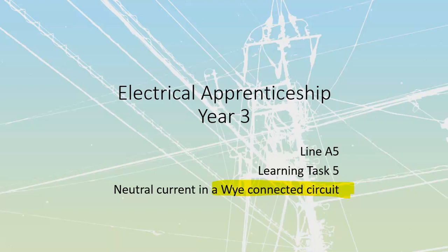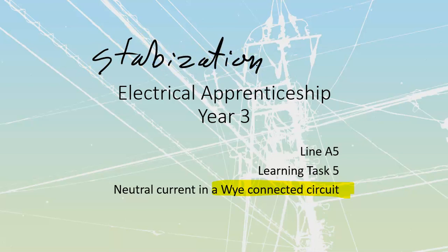So if we've got a single-phase load, the current gets delivered along the hot line, and then returns back along the neutral. The other point they have here is that the neutral is a convenient point for grounding the system, which improves safety. The neutral is going to be grounded, but more than that, it does something we're going to call stabilization. Let me just write that out. It is going to make sure that the voltages across our loads stay locked down. They're going to be constant. They're not going to be jumping all over the place anytime we get changes on the system itself. And so that is a really big reason why we use these neutral systems.